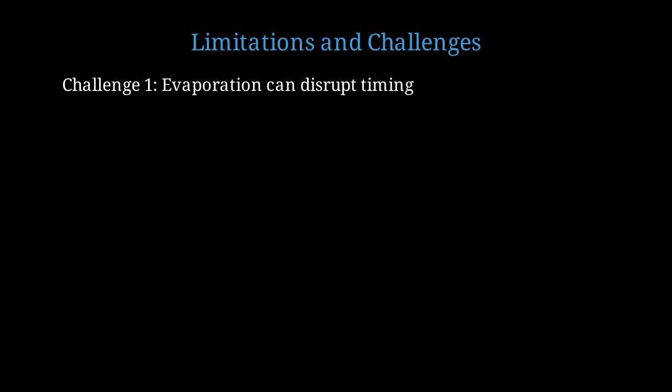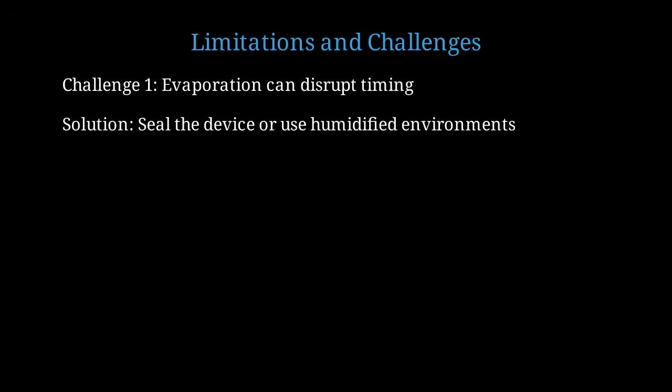Of course, these systems have limitations. Let's be honest about the challenges. First, evaporation can disrupt the timing if channels are open to air. Water evaporates, changing volumes and pressures. Solutions include sealing the device or operating in humidified environments.